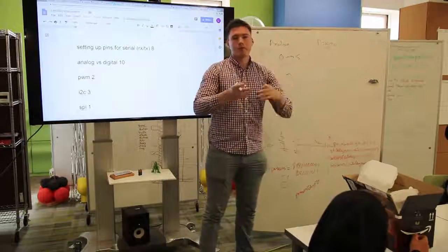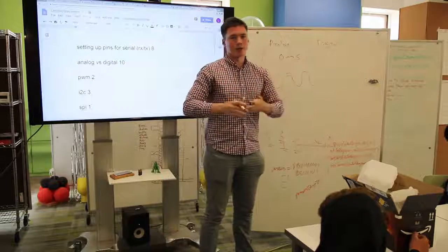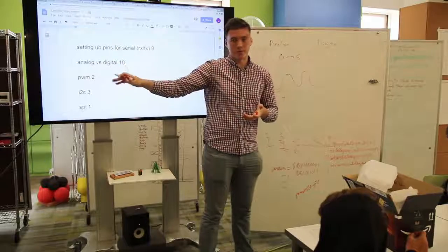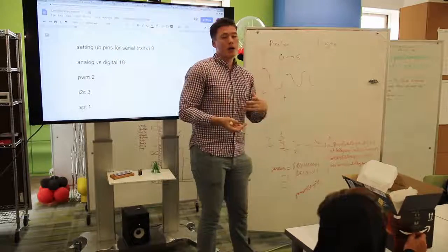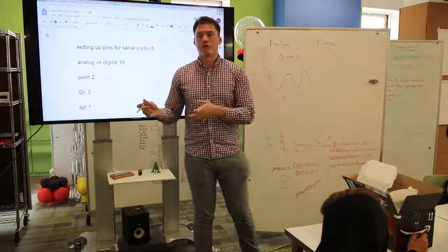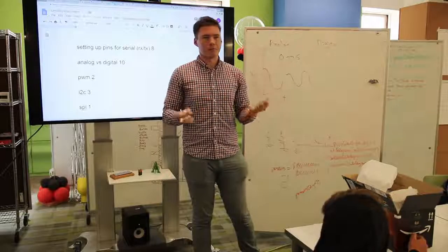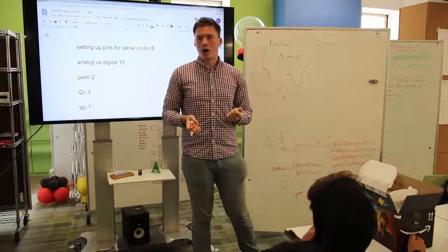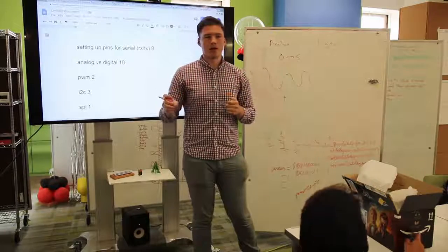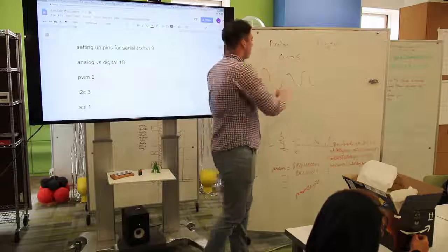Let's say you had 2 volts. Because it's a computer, it has to eventually take on some definite value. A computer can't store 3.333333, infinite. So eventually it has to cut it off, and it cuts it off at a total of 1,024 possible values. Does anyone know why it'd be 1,024, that specific number? Any guesses? It's slightly more than a byte. It's 10 bits, because 2 to the 10 is 1,024, so it can hold 1,024 different values.